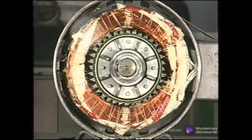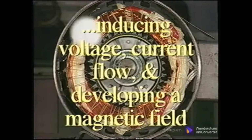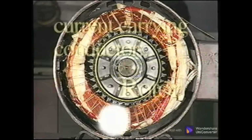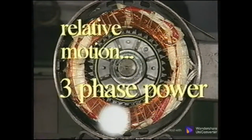The relative motion between the rotor and the stator causes the rotor bars to cut the stator's lines of flux. This induces a voltage on the rotor and causes current to flow, developing a magnetic field on the rotor. With the addition of the rotating field, all the requirements have been met to induce a voltage on the rotor: a current-carrying conductor, the rotor; a magnetic field, the stator; and relative motion between the two, the three-phase power.